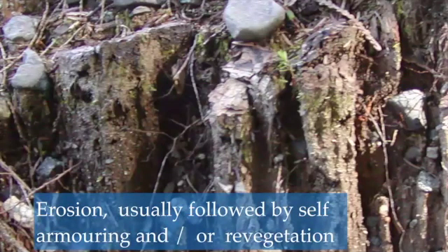When you look at rainfall erosion, wherever there is any surface material, a rock, a bit of moss, a twig, that is enough to protect the surface from rainfall erosion, and surface erosion is halted. When the surface is opened up, if there are particles of rock or organic materials, as they come to the surface, as the fines go away, then the rate of erosion will decrease dramatically as the surface hardens.